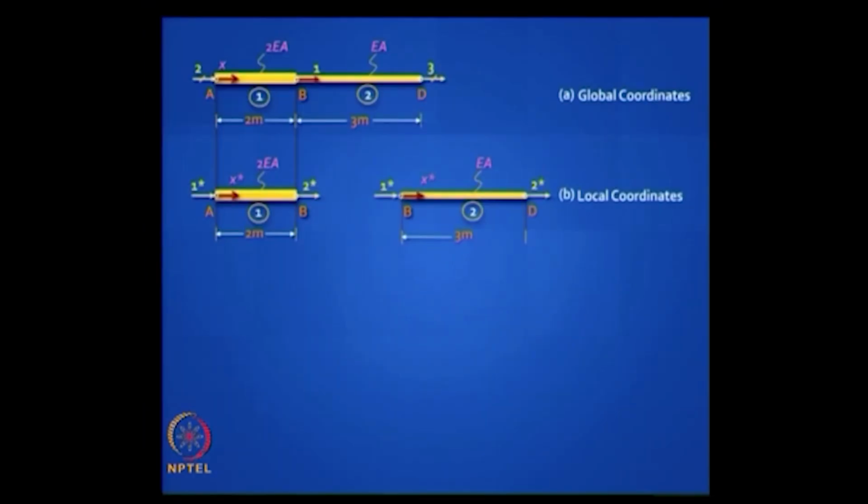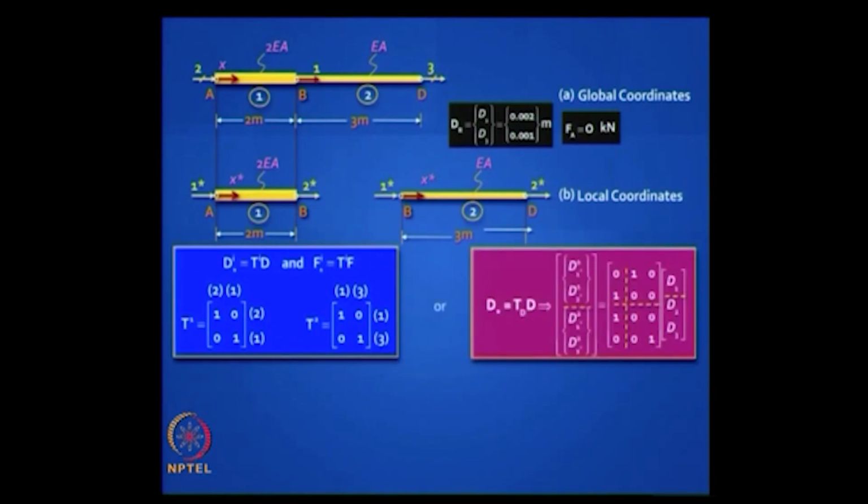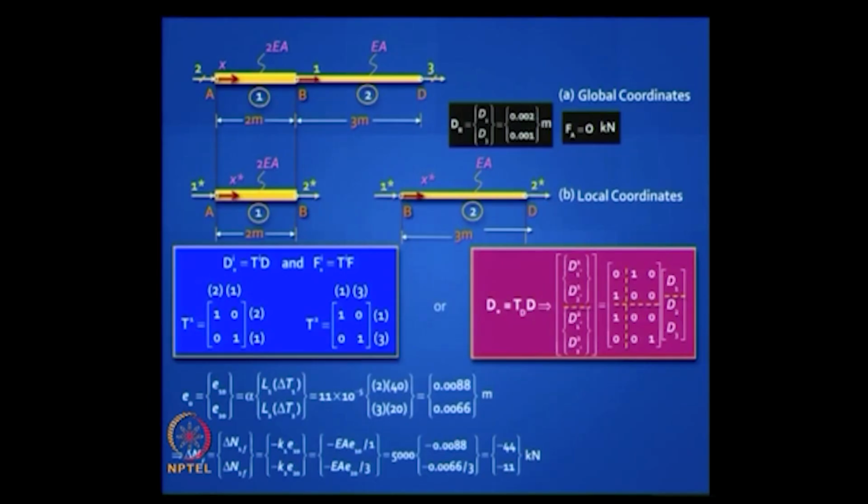Let us see how to demonstrate. So you have got global coordinates, you have got local coordinates, we do not waste time. This is the input data, you do not have a direct load vector, you have done these two calculations, either you do it by the TI method or you do by the TD method, both expressions we have. Now we calculate the bar elongations, there it is a rise in temperature, so E is positive. This step is straightforward, L alpha T, L is known, calculations are straightforward. What do you do next? You find the axial forces, they turn out to be compressive.